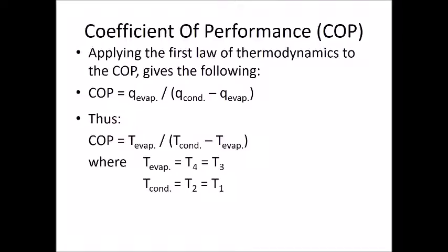So just as we would use any normal forward Carnot theory, I can turn those Q's just into temperatures. So I want you to write this down again here, which is in the case of a refrigerator, COP equals temperature in the evaporator versus the difference in temperature between the condenser and the evaporator.